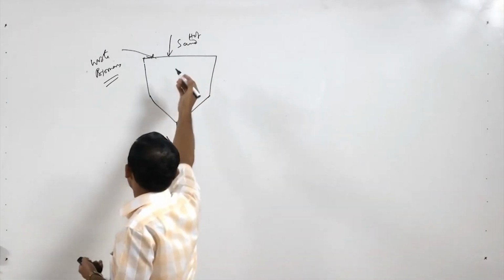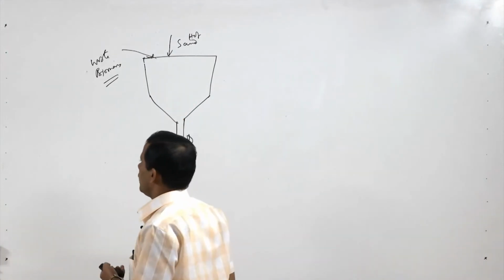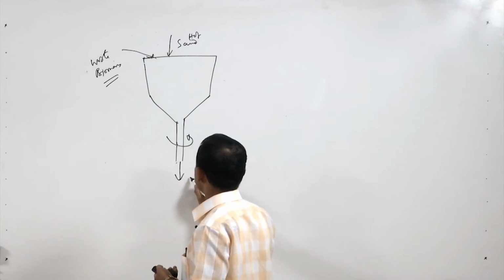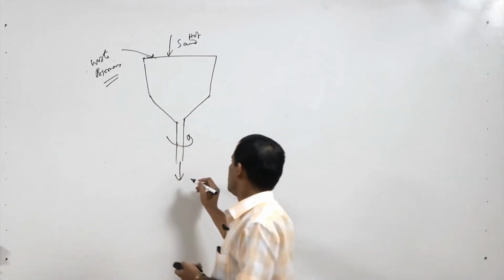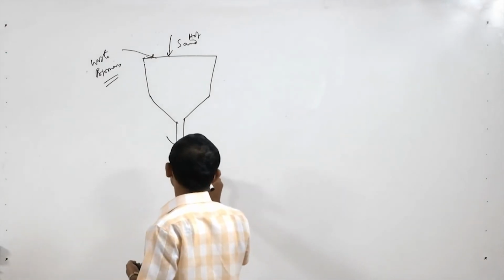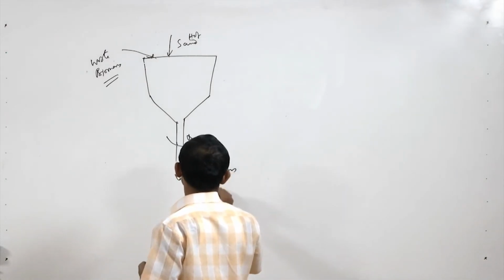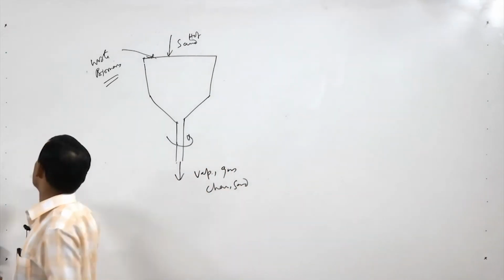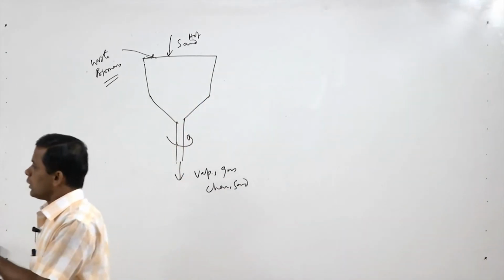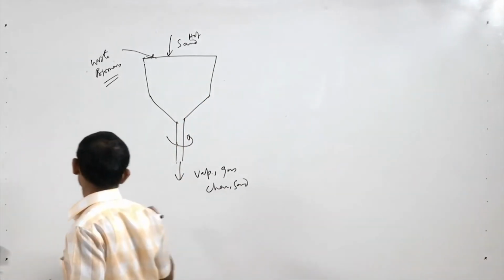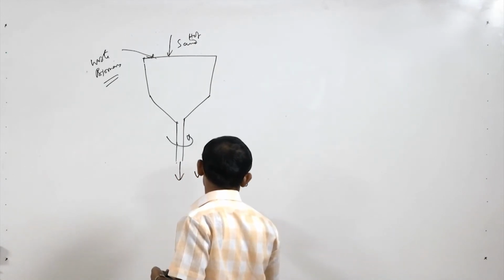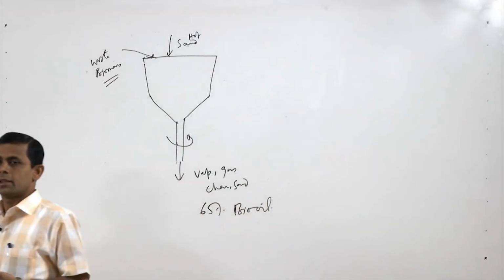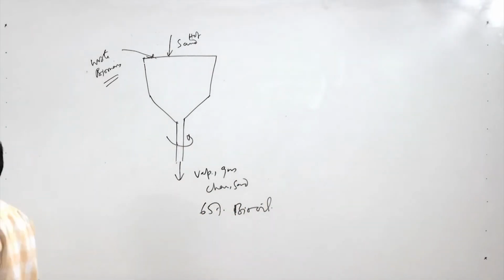As the hot sand is used with the material, the product comes out from the bottom. It takes less time and we get vapor, gas, char and sand, and after separation the sand can be added from the top once again. In this process we can get around 65% of bio-oil, but this reactor system also has a disadvantage, it is difficult to scale up.